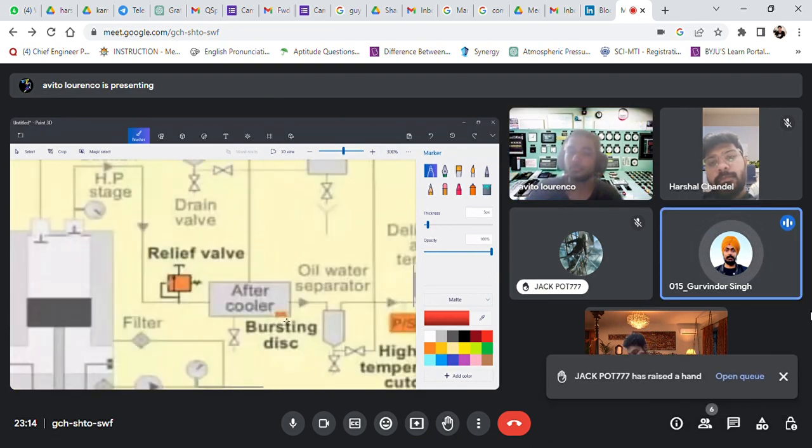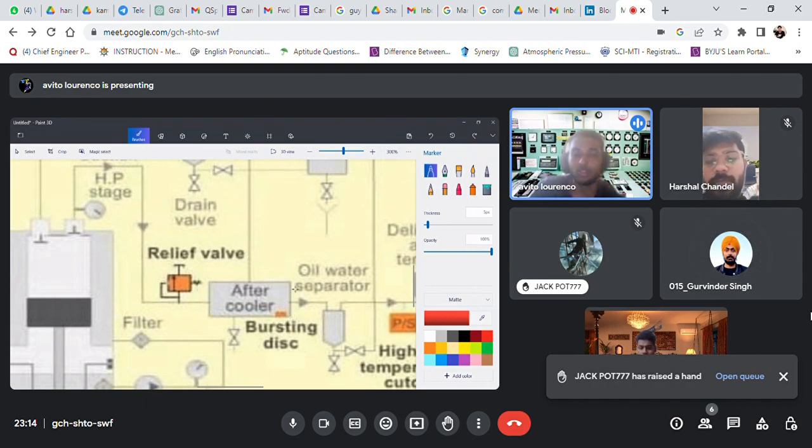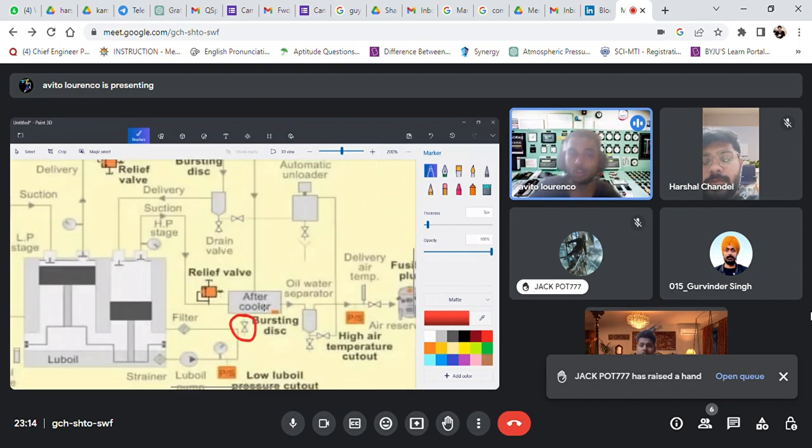It can also reduce the size of the air bottle. For the same capacity of air, I'll need a larger space otherwise. Okay, so that is another good point. So, any idea what this is over here? Why do I have this in the aftercooler but not in the intercooler?